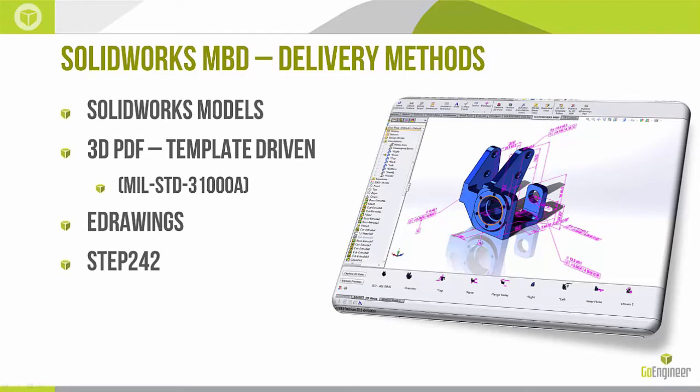So like I was saying, what MBD really gets you at the end of the day is the different deliverable methods. SolidWorks models are great deliverables, but it's really only limited to other SolidWorks users or other SolidWorks houses. The 3D PDF is extremely strong. eDrawings is another great way to look at different files that we create here if you don't have a SolidWorks license where you can open the native files. And then lastly is the STEP AP242 format. It's a new STEP file format that can actually capture some of this critical or important PMI information from the model in a CAD agnostic way, right? In a way that doesn't require you and whoever you're dealing with to have the same CAD software.